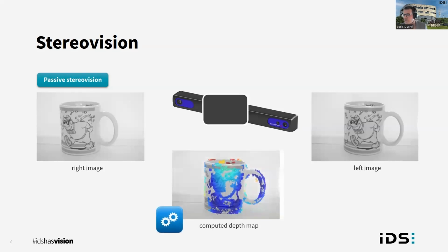In the example that you see in my slide, you have a lot of homogeneous areas. You have a pixel that is white, surrounded by pixels that are white, and you look in the other image if you can find the matching pixel, and you have so many possible candidates, so many that the matching algorithm will not work. This is a limitation of stereo vision cameras. They don't like homogeneous areas.